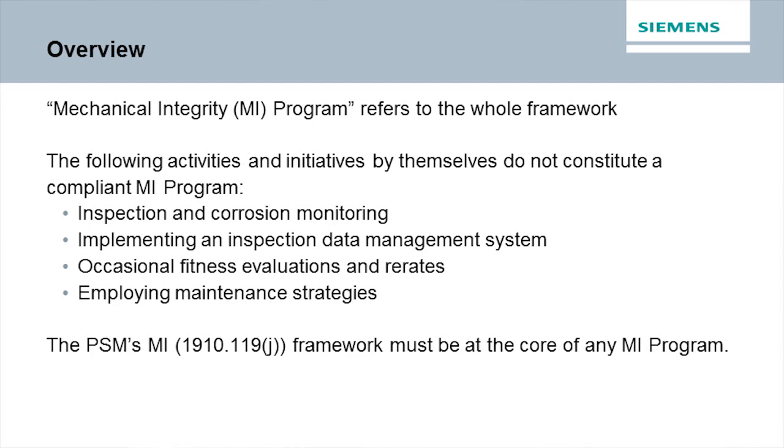As we know, the following activities that I'm going to mention below do not constitute a compliant mechanical integrity program, as others seem to believe, or as we used to believe. Inspection and corrosion monitoring by itself will not meet compliance. Implementing an inspection data management system will not meet the goal. Occasional fitness-for-service evaluations and re-rates are good, but by themselves are lacking in complying with the mechanical integrity program.